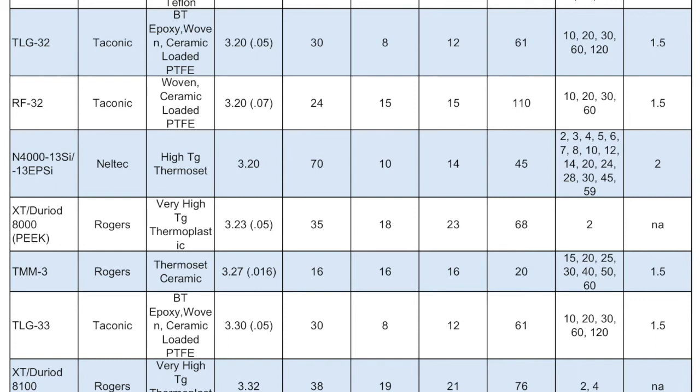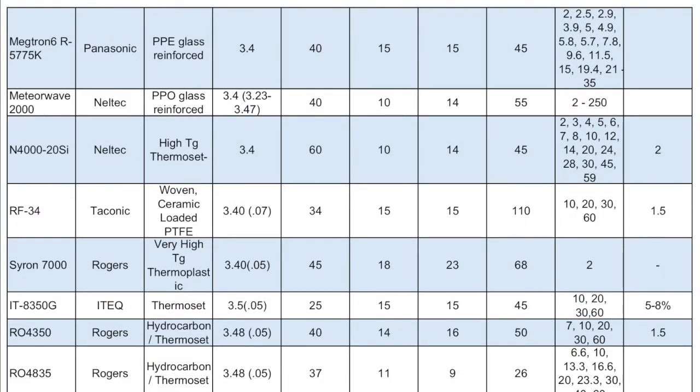Is there anything that you've seen that's, I guess, relatively new offerings for this type of product? No, not really. And the reason I say that is because these materials have been in development for a long period of time. But what we see is the offerings from the number of suppliers has increased almost exponentially. It seems like almost every thermosetting laminate manufacturer is now offering what we consider ultra low loss materials. And what that means is there's more variety. There's the ability to fine tune the designs to a higher degree than in the past.